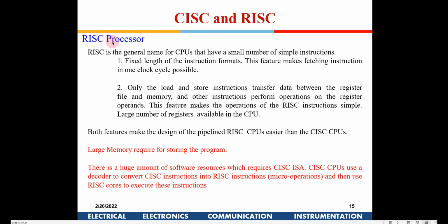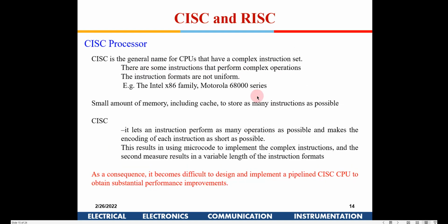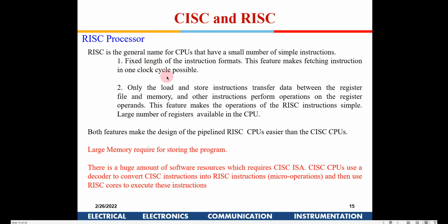In the reduced set of instructions, you can't have such complex instructions, and the length of the instructions will be fixed. It is only a single small instruction you can write. Whereas here, some instructions like increment A are single-byte instructions, while the MOV we discussed could be a 5-byte or 6-byte instruction. So the length of the instruction is different in a CISC processor, whereas in RISC the length of the instruction is fixed. There will be single-line instructions. It could be 8-bit or 16-bit, but it will be fixed.